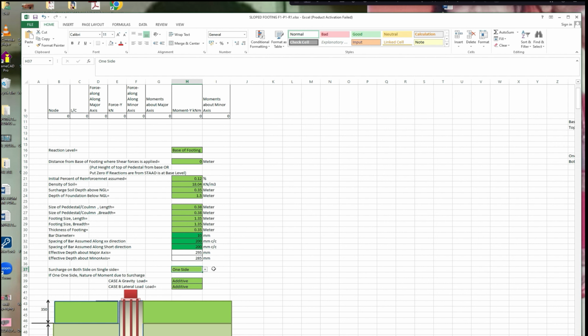One more thing, in this detail sheet, I have taken structures on the footing on one side. That is because the plinth level is always at a certain height from the natural ground level. So for adjustment, there are many adjacent columns in which the footings will have structures on a single side only. So we should consider that as well.